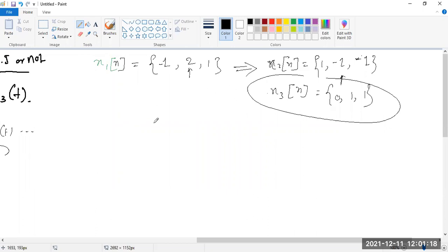Just think of it. First we can take a shifting operation, x1[n-1]. n-1 means a shift over there. So if this is the 2, it will shift here. We can say this is 0, 1, 2, 1. The origin arrow will be shifted over here because this is minus 1, and that's why here is nothing, so we put 0.